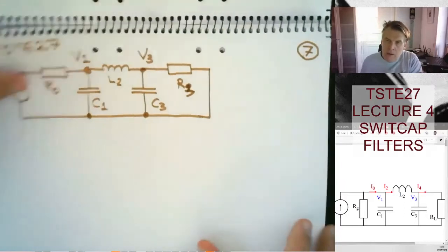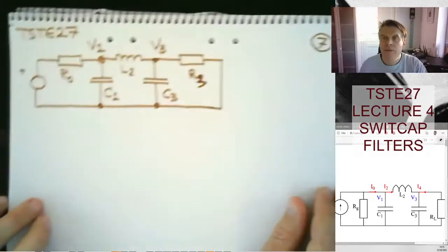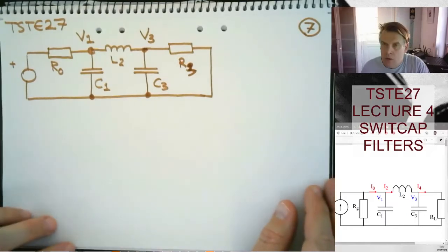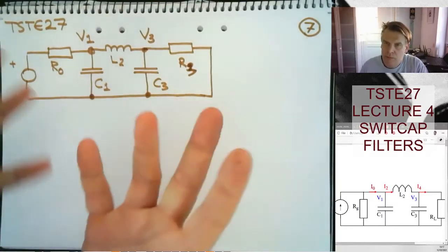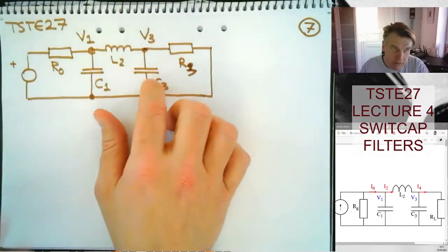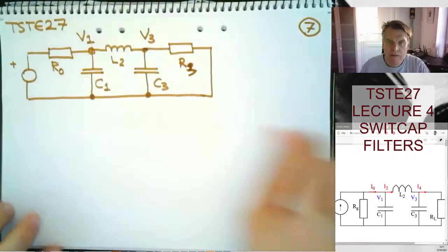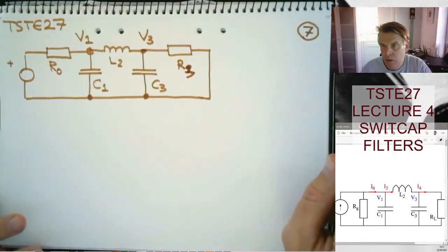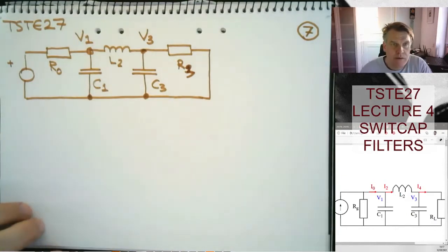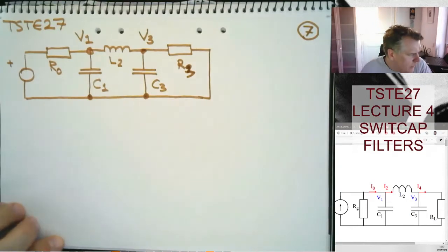This LC ladder network gives us shorter paths from input to output, and there is also a certain spread across the whole filter. So a small error in one path is replicated and distributed to the entire signal chain in your filter, which has some nice properties. A filter specialist would be able to explain that much more in detail than I can.